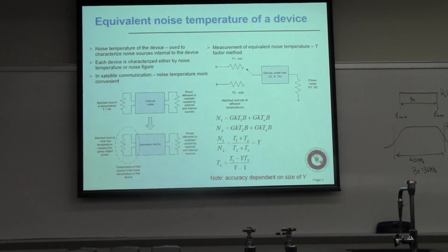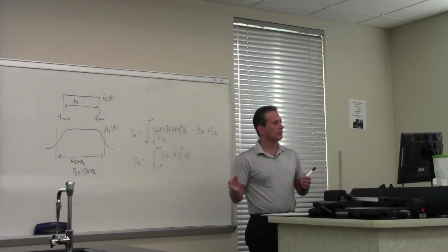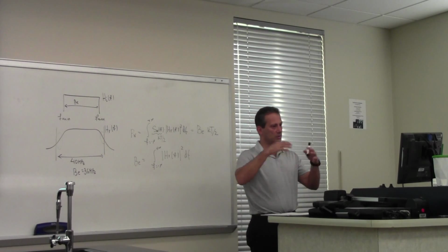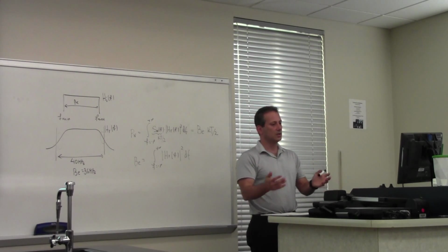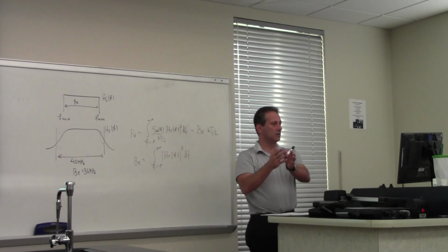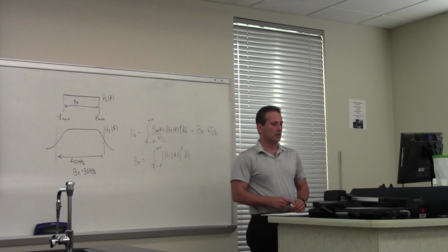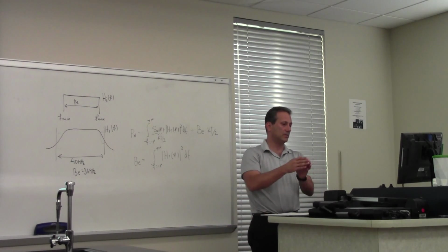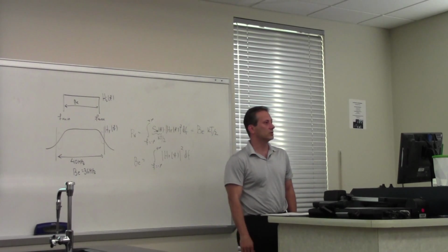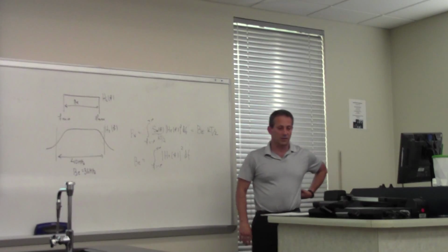But you will see very soon that when it comes to the noise calculations, we'll do quite a few of them. You will see that the noise figure of the whole system, and what is important for the noise analysis, is determined by the first couple of stages of your receiver. The noise figure of what comes below, after the first LNA, diminishes in importance when it comes to the noise figure. So we'll go through the detailed calculations.